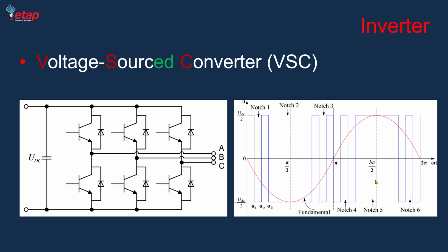As you see here on the right hand side, it generates a pulse of DC voltages at the output terminals of the inverter. It doesn't instantly look like a sine wave, but once we put some filters on the AC side, we can draw the fundamental frequency component that behaves more like the red waveform, which is our sinusoidal signal.